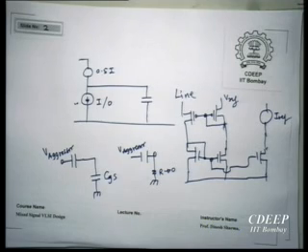So essentially what it means is that this circuit has all the good qualities, low power, high speed, low noise, everything, but it is not very kind to mismatches. Okay, so it's due to mismatch. After all, this IREF is being generated locally, and this is coming from a remote situation. So therefore these two cannot be ideally matched. So if they come very close to each other, then your circuit will become extremely slow. So your speed variation is very high in these circuits.